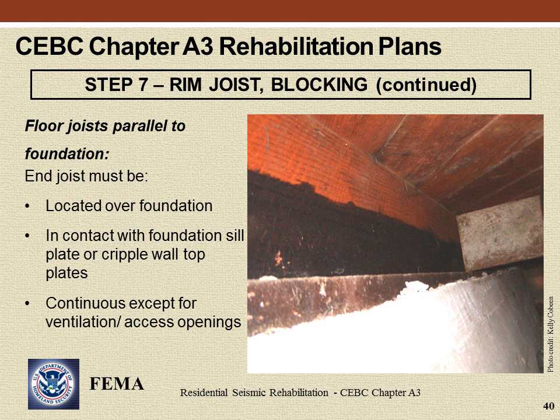At the sides of the dwelling where floor joists are parallel to the foundation, additional items need to be considered. The end joist or rim joist must be located over the foundation, in contact with the foundation sill plate or cripple wall top plate, and continuous except for access and ventilation openings. This photo shows an existing continuous rim joist parallel to the foundation sitting on a foundation sill plate. Standard floor joist blocking appears at the right-hand side.